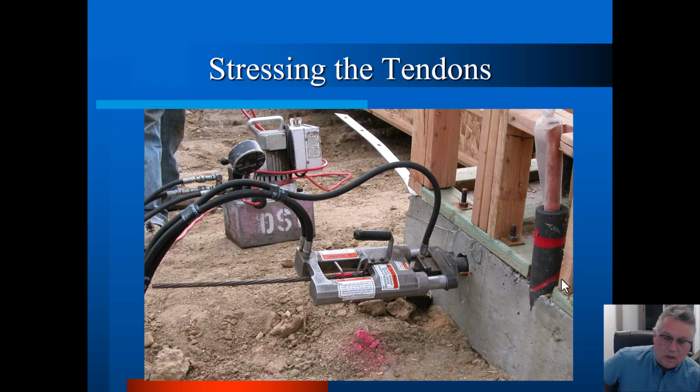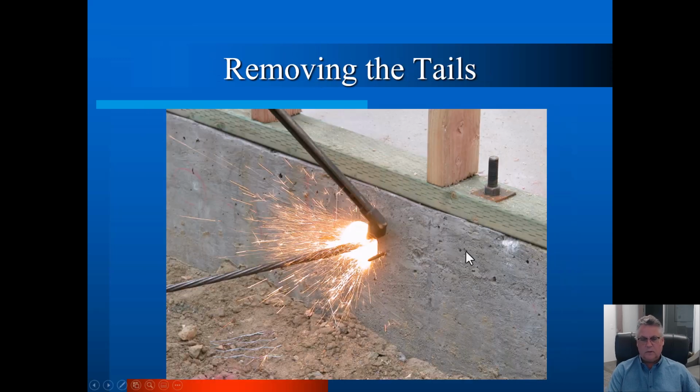This hydraulic jack will be placed, and the nose piece goes in where that plastic former used to reside. This will be hydraulically pulled back, stretching the tendon, which is being grabbed right here. So that's how the force will get in every single one of the strands inside the building. Then, as we saw in the video, this will be burned off.